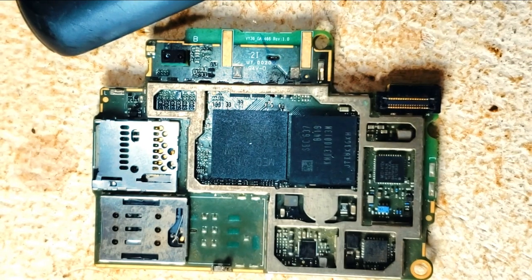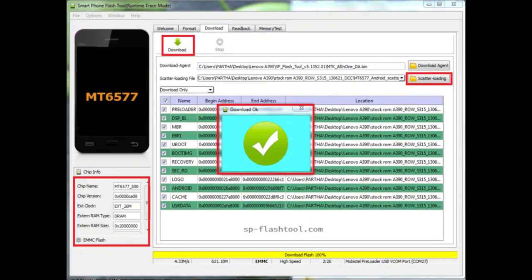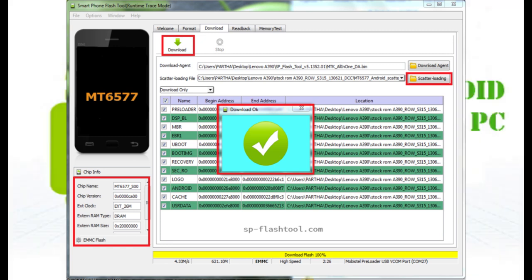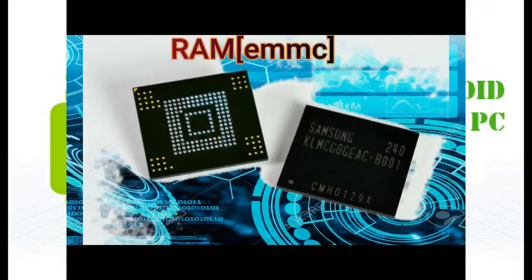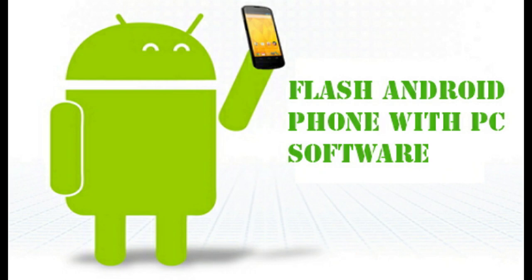This IC is also referred to as EEPROM, memory IC, ROM and RAM. When flashing of software is done on a phone, this is the software-hardware component that accommodates the system software. A faulty flash IC results mainly in software problems or power problems.